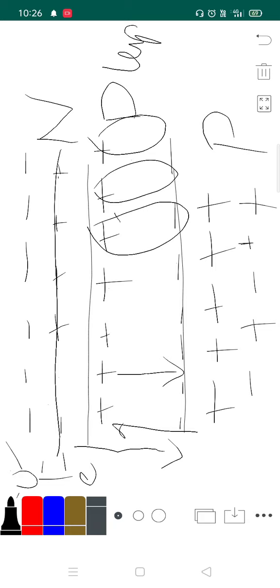Then electrons move towards the n region, and holes move towards the p-type region, due to the electric field developed in the depletion layer. On connecting the electronic circuit, electrons flow, generating electrical current for electrical circuits like a bulb.